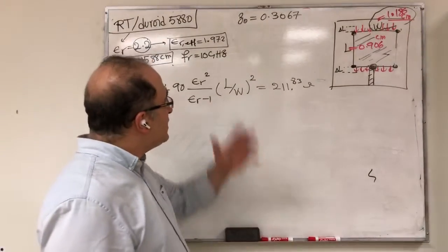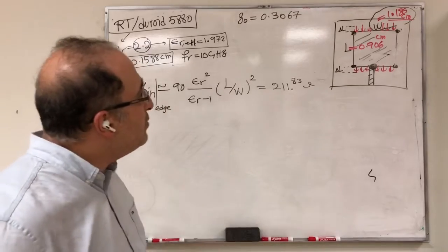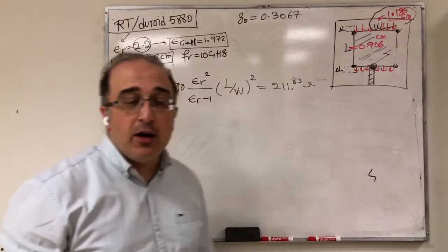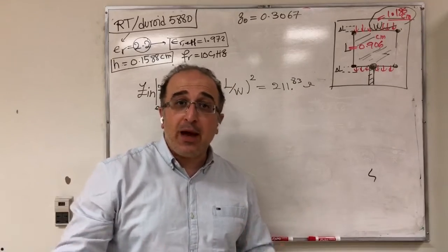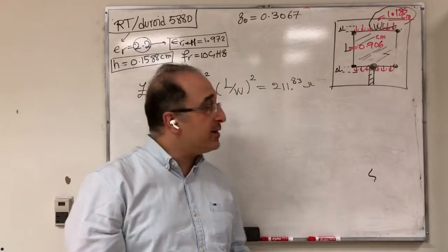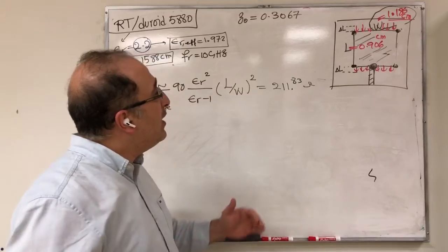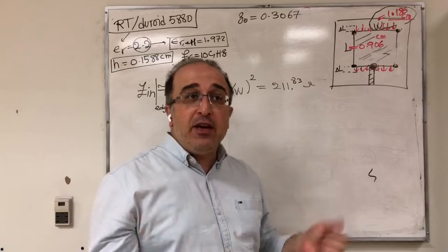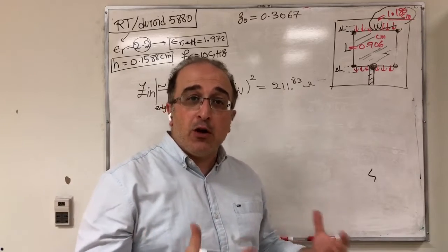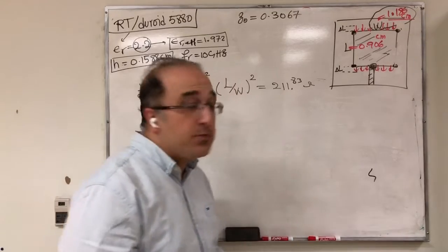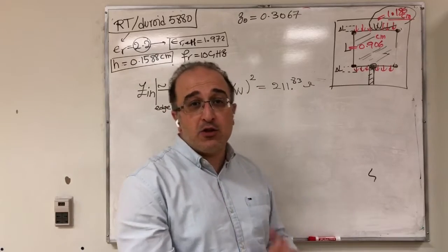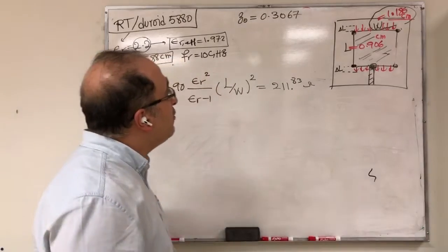We arrived at this point and realized that the input impedance at the edge of the microstrip antenna is very large, so it makes matching to 50 ohm complicated and challenging. Therefore, we're looking for ways to alleviate that and come up with a scenario that gives good impedance matching, because at the end of the day, you need to give the power to the antenna elements for it to radiate.